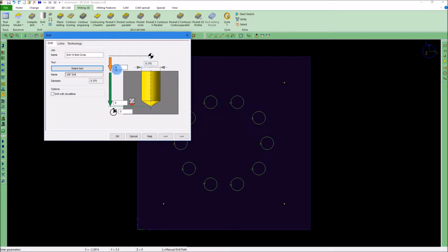This entry represents the distance from the drawing axis to where we wish to reference all the other drill Z movements from. Normally this is just 0, especially for a router where all Z values specify a distance above the machine table. However, if you wish to work from the surface of the material, or if the axis is at a different Z height for other operations, you have a place to make this adjustment here. For this example, since we want Z equals 0 to be at the bottom of the material, and that is where the axis currently is, we will leave it 0.